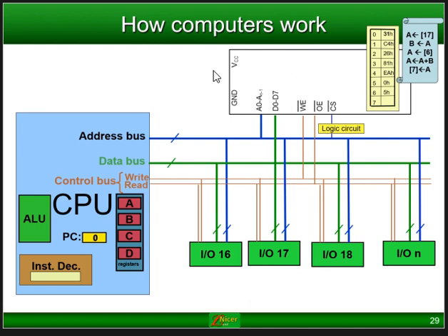How does it work? So you can see the program counter. First of all, it will place 0 on the address bus. So it actually says it wants to talk to address 0. Now in this specific case, that's address 0 there. This is address 1, 2, 3, 4, 5, 6, 7. And this is 16, 17, 18, and 19. At this stage, they're not addressing 8, 9, 10, 11, 12, 13, 14, and 15, for instance. But okay, so let's have a look now at what's going to happen.